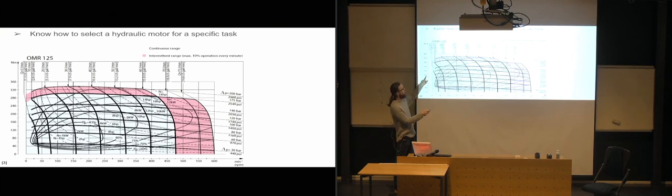If we have 160 in momentum, we go over there, that's approximately here. We can see that the pressure line going through there is 100 bars. So that means we have to deliver 100 bars into our motor in order to gain 400 RPMs at 160 Newton meters.